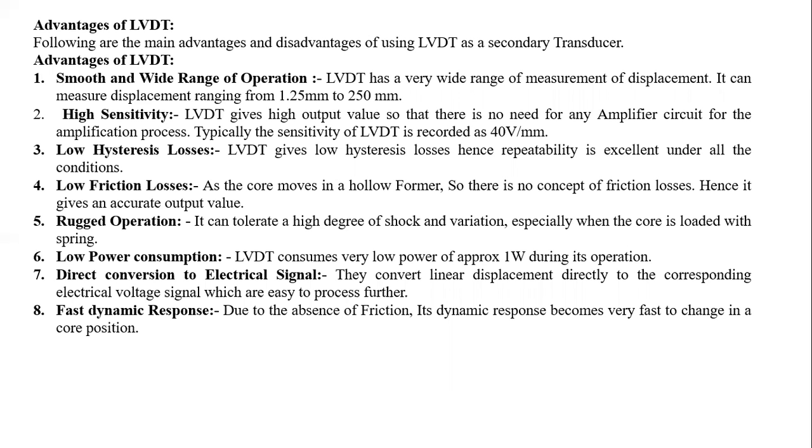Low hysteresis loss: LVDT gives low hysteresis losses, hence the repeatability is excellent under all conditions. No frictional losses: as the core moves in the hollow former, there is no friction loss, hence the output is accurate.